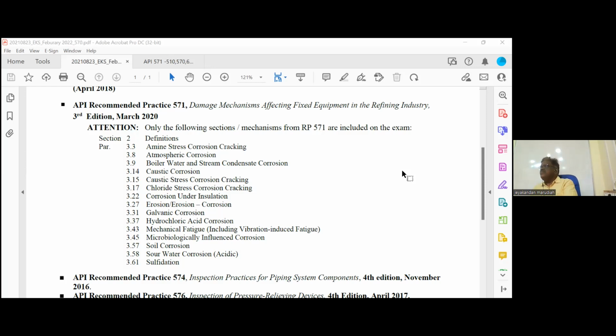So what are the different types of inspection we have in piping? In a large pipe, we can go inside and check. That is called internal inspection. Generally, internal inspection is not carried out on piping because the size is small. Internal inspection means checking the inside condition from inside, which is practically not possible for most of the piping. Only large diameter piping we can go inside. The second one is the external inspection, checking the outside condition from outside without NDT. So there will be no NDT actually.